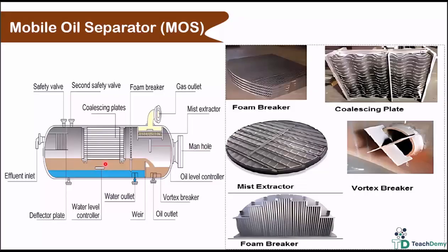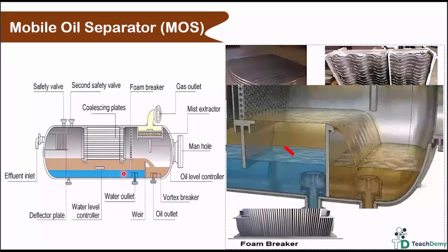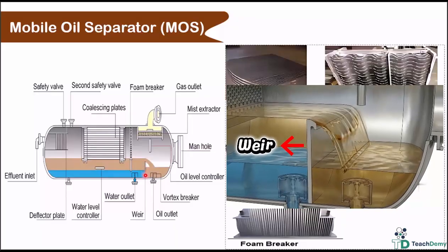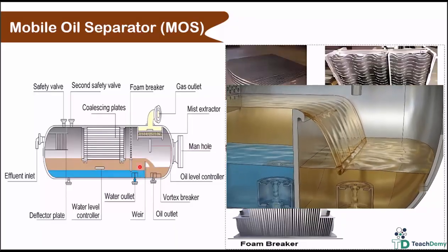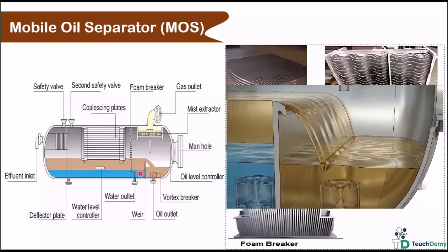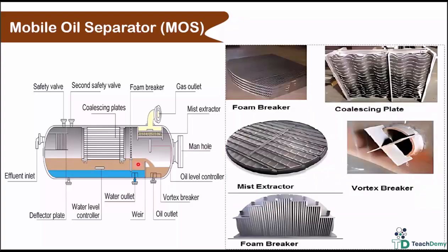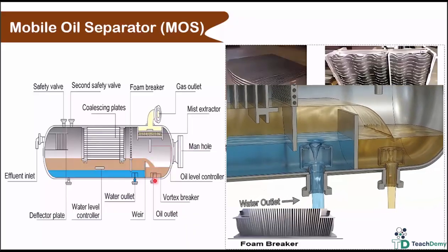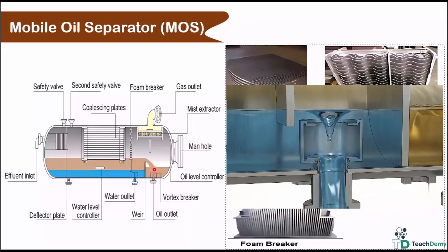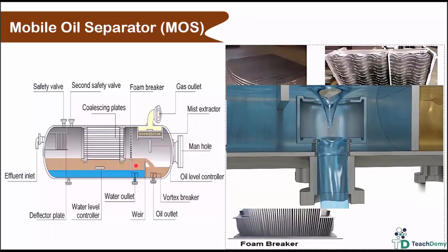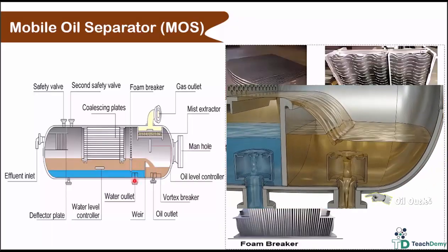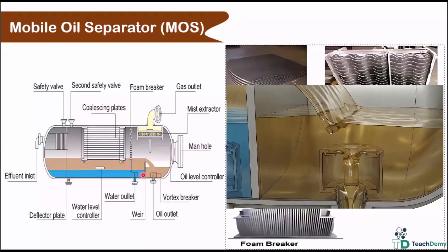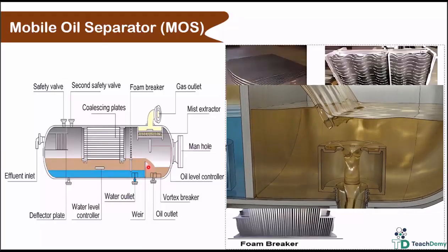To separate water from oil, the flow passes through a weir, which operates based on the density difference between the two phases. Lighter oil gradually separates from water, and when its height exceeds the weir, it moves over the top toward the oil outlet, while water is directed through the lower section under supervisory control. The weir also helps smooth the flow, creating laminar conditions for more precise separation.